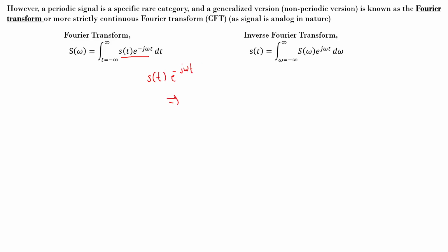So this is something like a demodulator, right, with omega. So basically you are multiplying the signal with a sinusoid which is actually centered at omega. So any component in this particular signal which is at omega will come to 0, DC frequency. So that is the meaning of it.